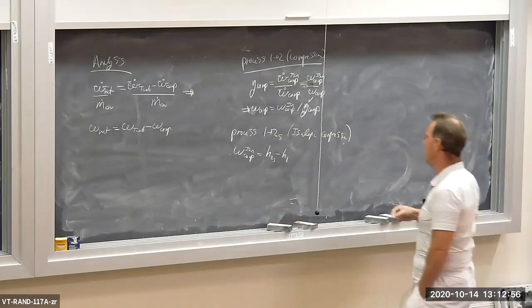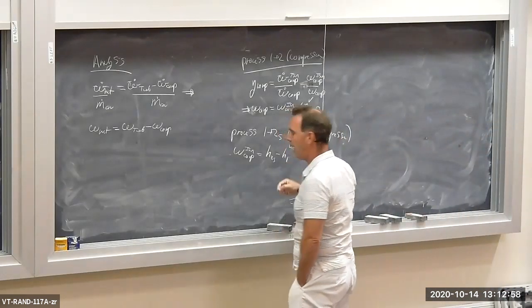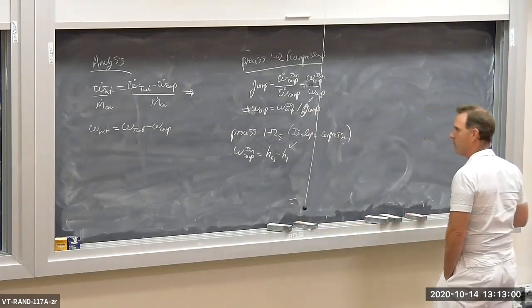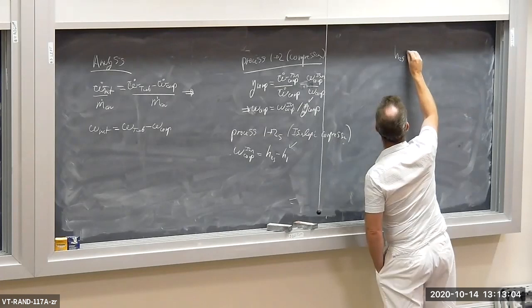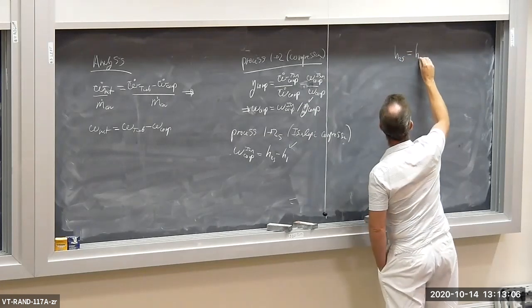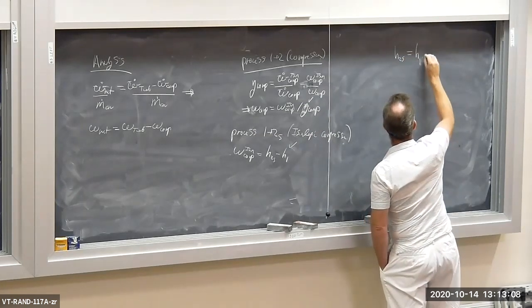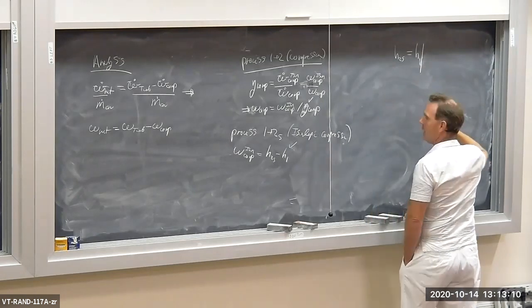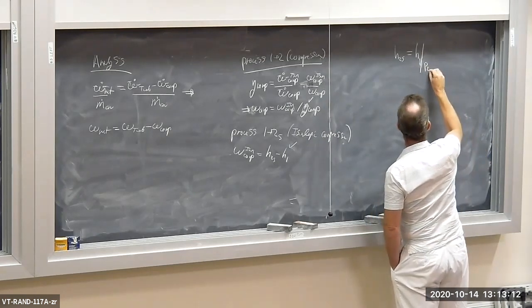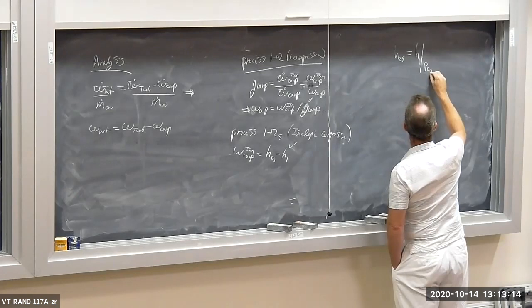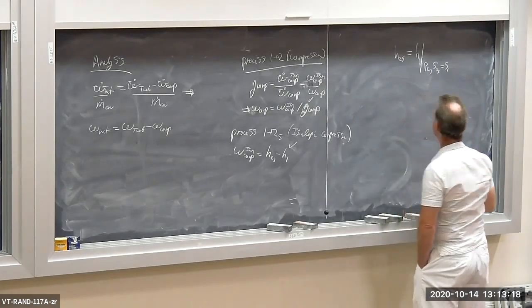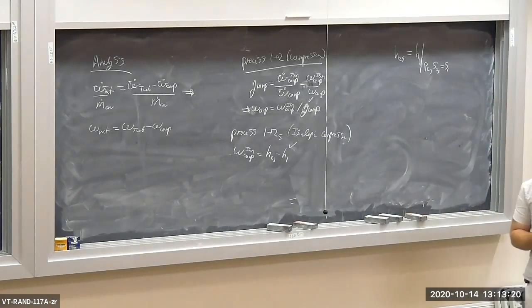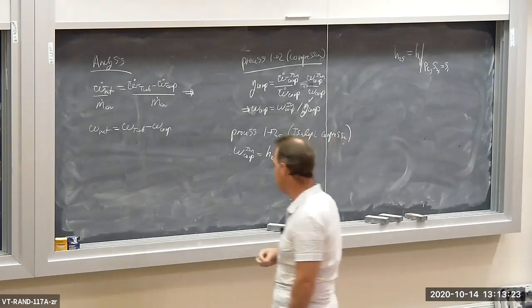So I know H1. I don't know H2s. H2s is H evaluated at pressure P2 and S2s equals S1. So it's an isentropic compression process where pressure is equal to P2.